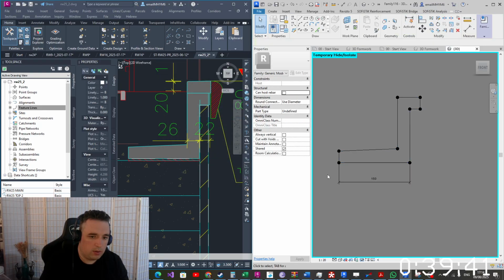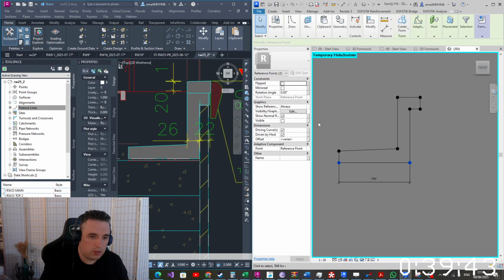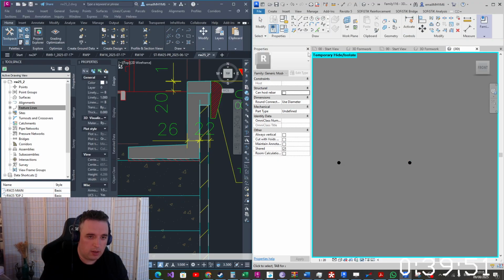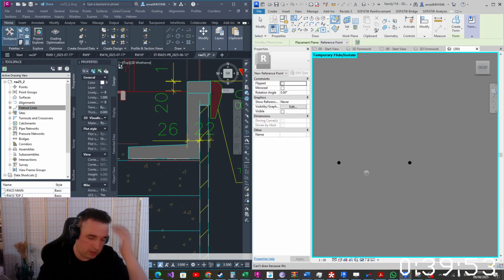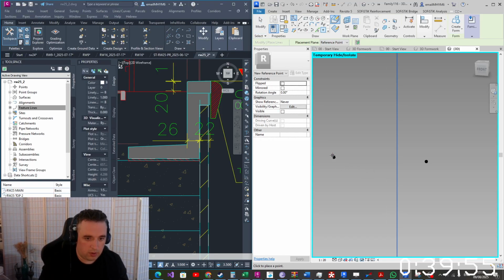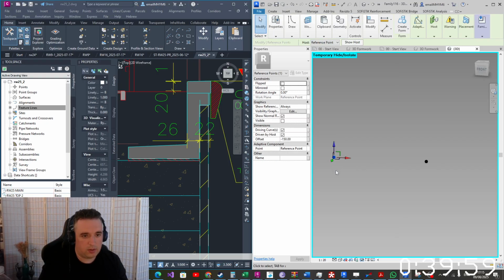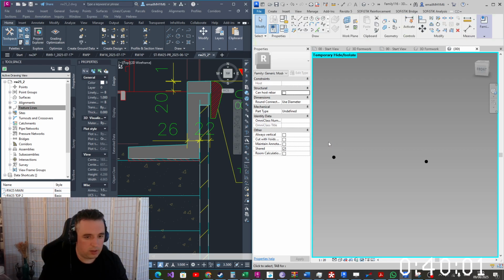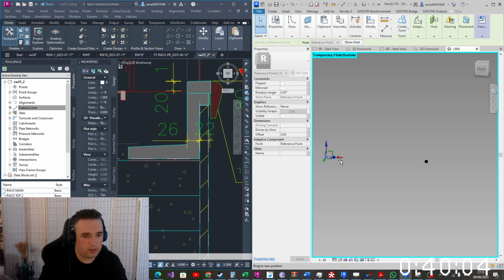Now we're gonna do the blinding concrete, which for us is always 5 centimeters. Outside and down. You know, it makes sense not to try and optimize these sorts of things, like make your drawings always so that when someone sees your drawing, he knows, okay, the blinding concrete is always gonna be 5 centimeters. So I don't need to bother.